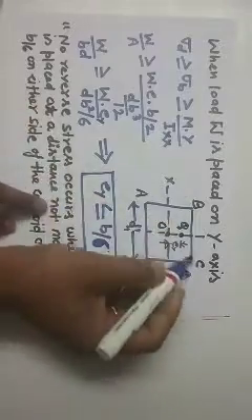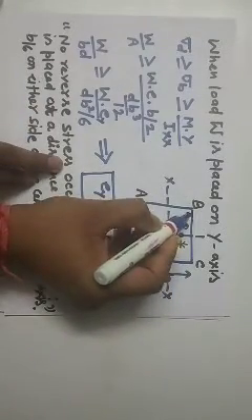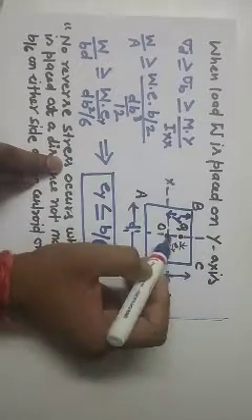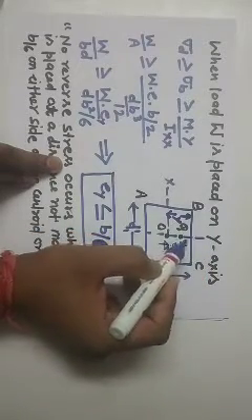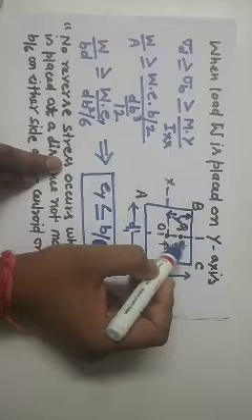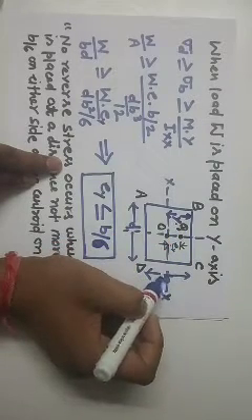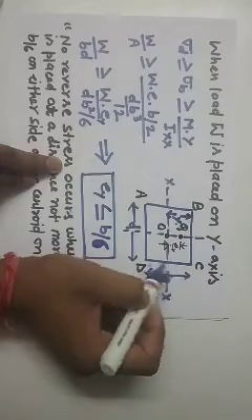Here y will be equal to b by 2, because the load is placed on the y-axis, so the distance of the top fibre from the centroid is y max, which is b by 2, because this dimension is equal to b.